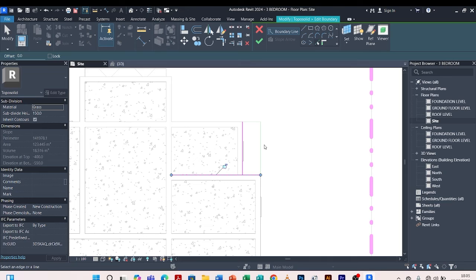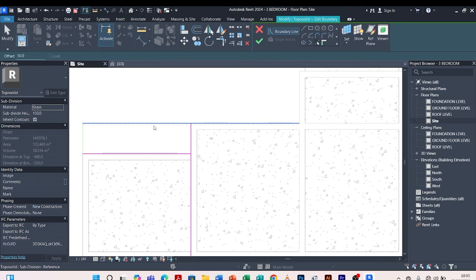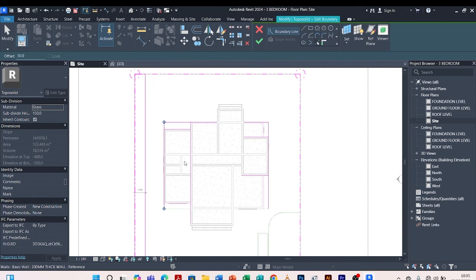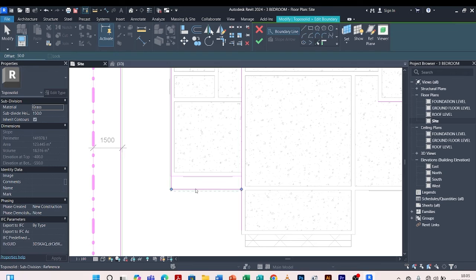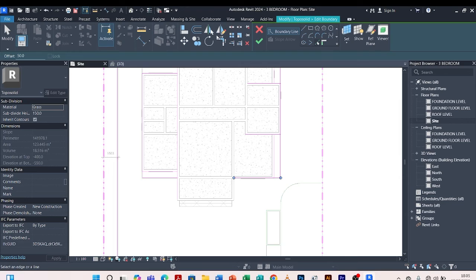So I'm going to offset by 75 inwards so that I have the curbstones. Let me give them 50 specifically for these planters around the house. So I'll have this inside, this inside, this inside, this inside, this inside. So I'm going to split this and also this, because it is serving the same purpose also on